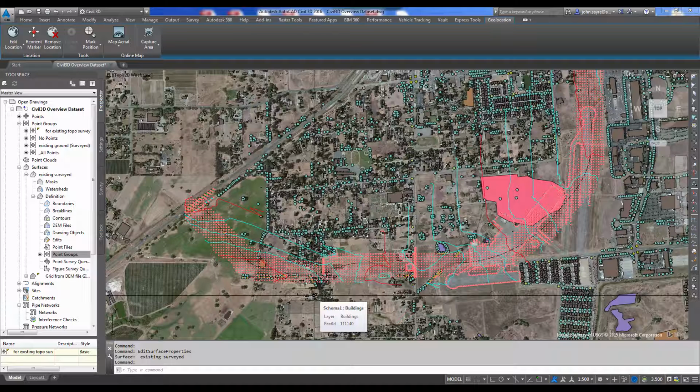So it'll basically just be opening up the surface and changing the style, and it'll look the way that you want. This not only helps you when you're trying to represent something in Civil 3D, meaning the style is already built for you in the company template, but it also standardizes the look for your company so that you can make standardization a little bit easier.